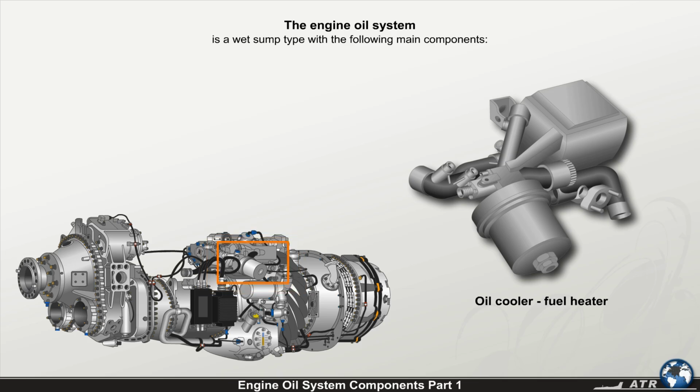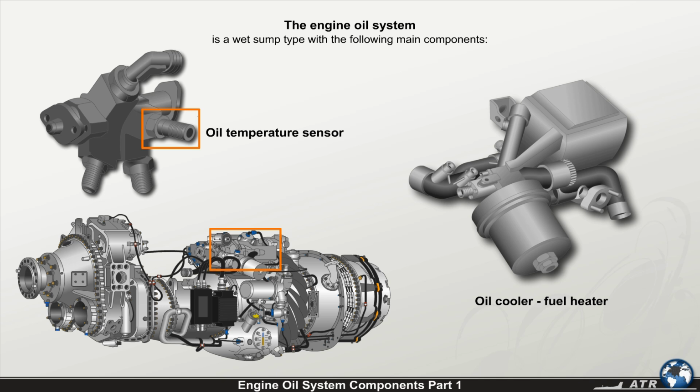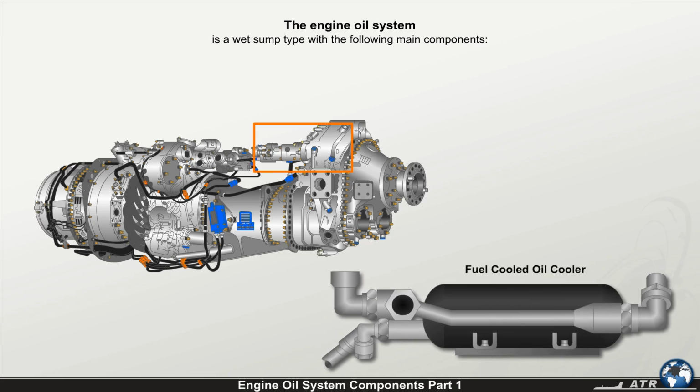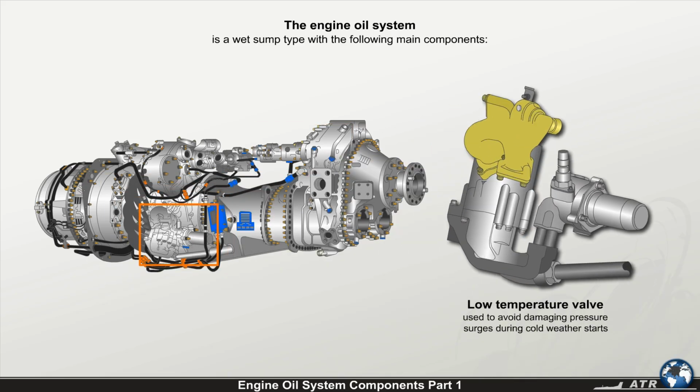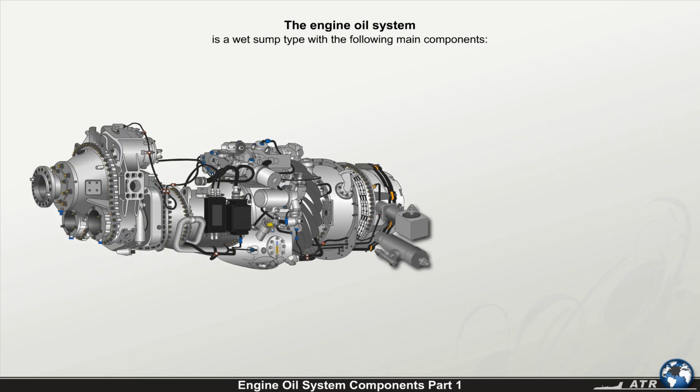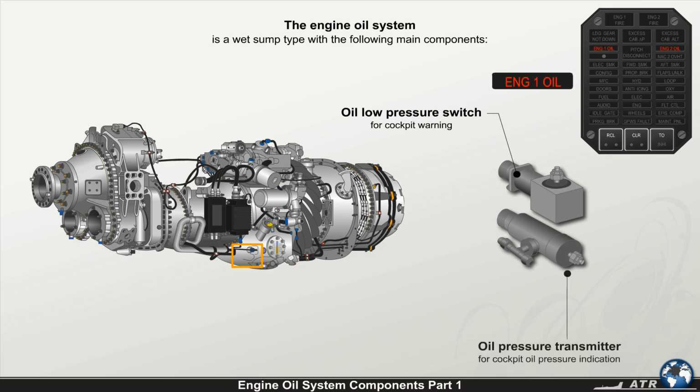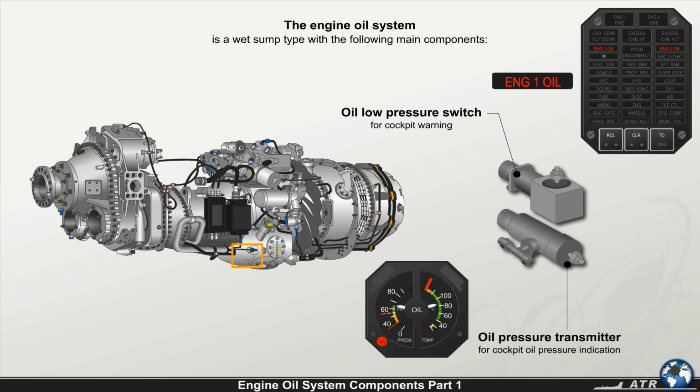An oil cooler, fuel heater, an oil temperature sensor, a fuel-cooled oil cooler, a low-temperature valve used to avoid damaging pressure surges during cold weather starts, an oil low-pressure switch for cockpit warning, and an oil pressure transmitter for cockpit oil pressure indication.